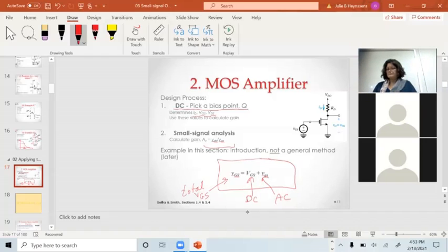And then is that AC part using the gain in the small signal analysis equation, or is that still big VGS? The gain in the small signal analysis, the equation just above, that is little v, little g, little s, or it should be. When I'm handwriting it, I usually just use a little cursive version of a v to say that it's small.